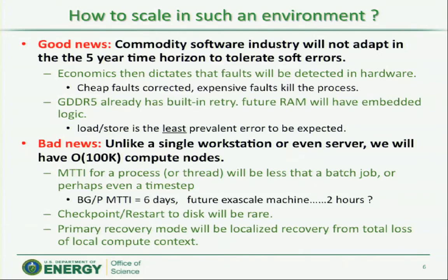So you're going to have ECC or SEDC, double or single bit correction. Because memory is banked, you're going to have this problem of chips occasionally dying, and you're going to replace them based on whatever the maintenance schedule for the machine is. You all get the email from the center saying we're going down for scheduled maintenance. That means right now there are probably about 45 to 500 chips on the machine, or components of the machine, that are misbehaving. They're not executing correctly, but the machine is still up. Those nodes are still scheduled.